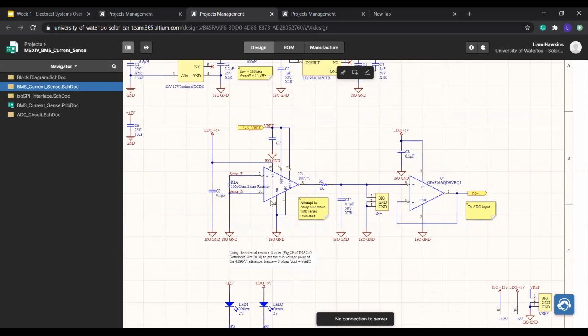So anyways, this is a current sense amplifier. It's basically just a regular op amp, but it has a very precise gain of 100. So the output will be 100 times the input. And that's referenced to a 2.5 volt reference that's generated by the ADC on this board. So what this means is that if the output would be -1 volt, then because it's referenced to a 2.5 volt reference, it will actually output a 1.5 volt signal instead of a -1 volt signal.